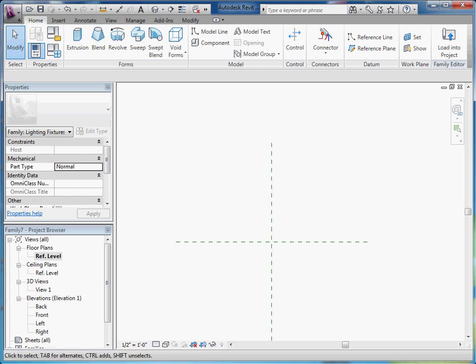before we start drawing out any geometry, if you want to make this thing parametric, meaning you want to set up parameters that someone can later adjust, then you really need to lay it out by using reference planes. Because it's these reference planes that are dimensioned and move, and that's what will make the model move and change shape and size. So to make our basic box, we're just going to lay down reference planes that define all of its edges.